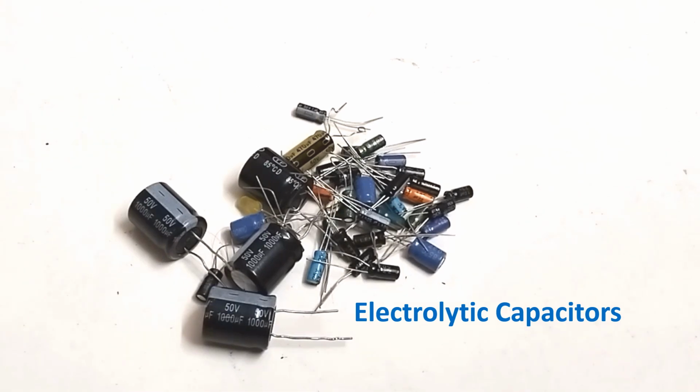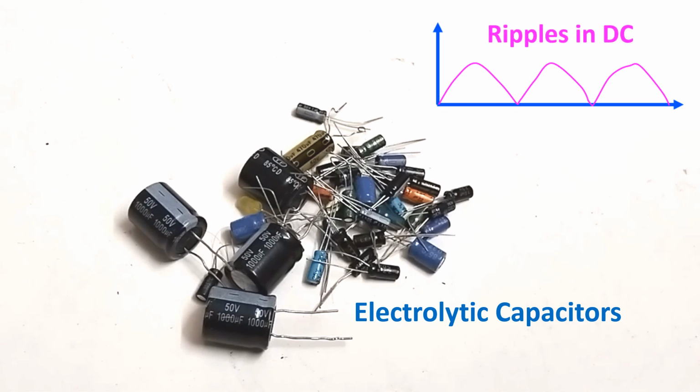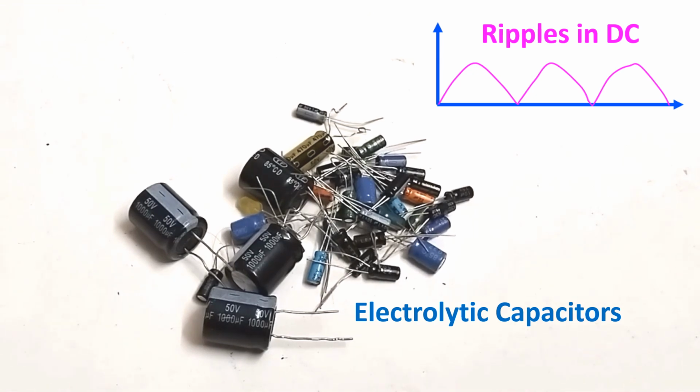Filter capacitors are used to smooth out the ripples in rectified DC. That is, when you use a diode, rectifier diode to rectify AC to DC, there will be ripples. Ripples in a rectified current can be smoothened by using high value capacitors like this. This is 1000 microfarad. You can use 2000 also, and multiple capacitors in parallel as well to smooth out the ripples in rectified current.